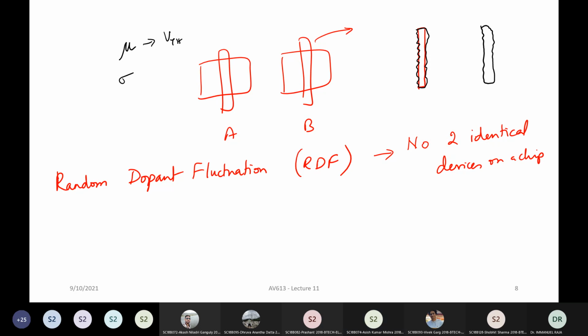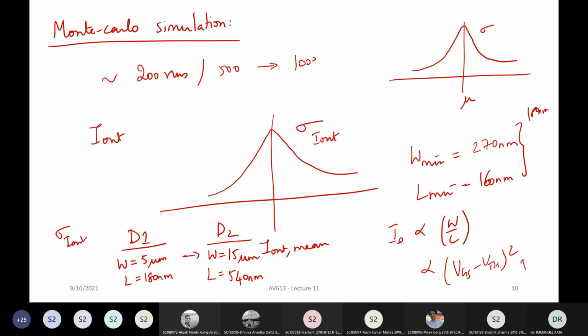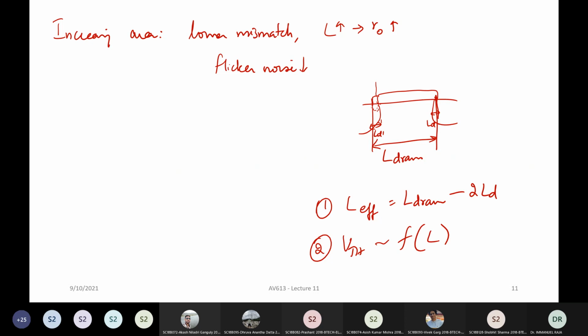So for all these different reasons, it is a complete no-no in the entire analog IC design community to ever change the channel length. You change the channel length, you change it for all the devices. That's like the holy grail of things. You don't touch it because of all these different issues that you will encounter the moment you have different channel lengths.